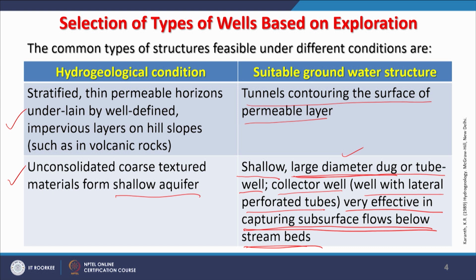When water comes into the well through the sediment, it automatically gets filtered more or less by natural processes, and then you pump out that water. That is a large diameter well, the example I showed of Devprayag.